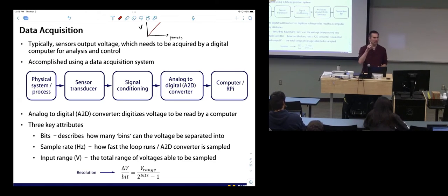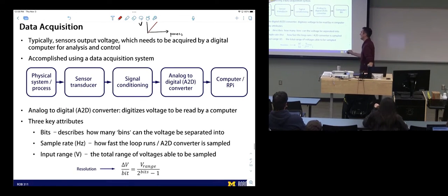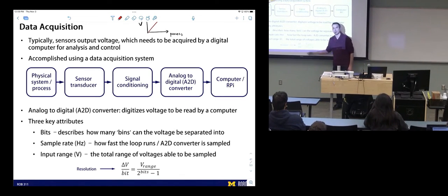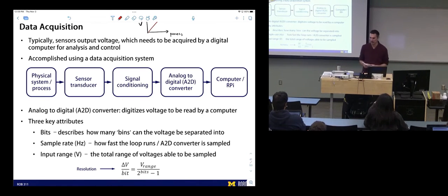Your sensor only goes to plus or minus 5 volts, but your data acquisition system is set up to receive plus or minus 10 volts. Is that good or bad? Bad. Why is that bad? We're losing resolution by half. Yes. If we match our sensor range and our input voltage, then we're maximizing the number of bins we can store that data in. The resolution was defined by this, and changing this number changes the resolution, as in the verbal example we just gave.